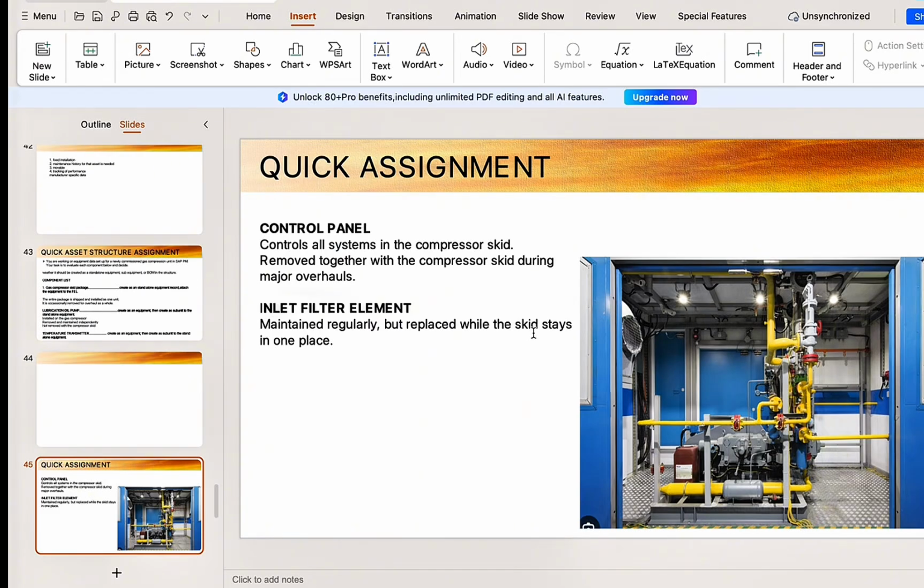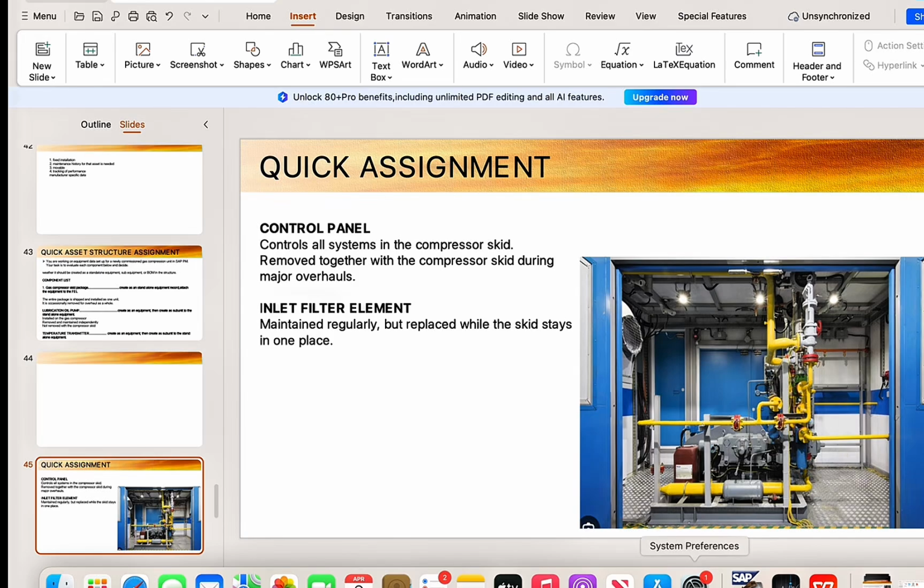So we're going to go again to create an equipment bill of material, and we can obviously do that through bill of material here. So I'll expand this and click on equipment, boom, click on create. Okay, so I want to attach it to the skid, and the skid is 30. Adding, I'll input my plant. I'll click enter. So your BOM usage, which is 4 for plant maintenance, and enter.